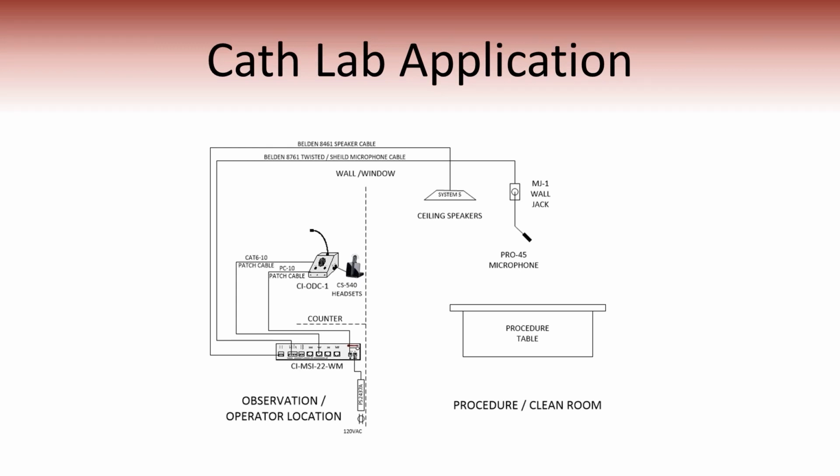Those are to get rid of basic high frequency anomalies in the room, but there's also notch filters built into the MSI so that if there is a coupling between speaker and microphone that's relative to a dimension of the room, there are 2 notch filters, a high notch filter and a low notch filter, built in here that allows you to take those frequencies and reduce them by up to 18 dB, so you eliminate the first 2 primary ring modes in the procedure room.